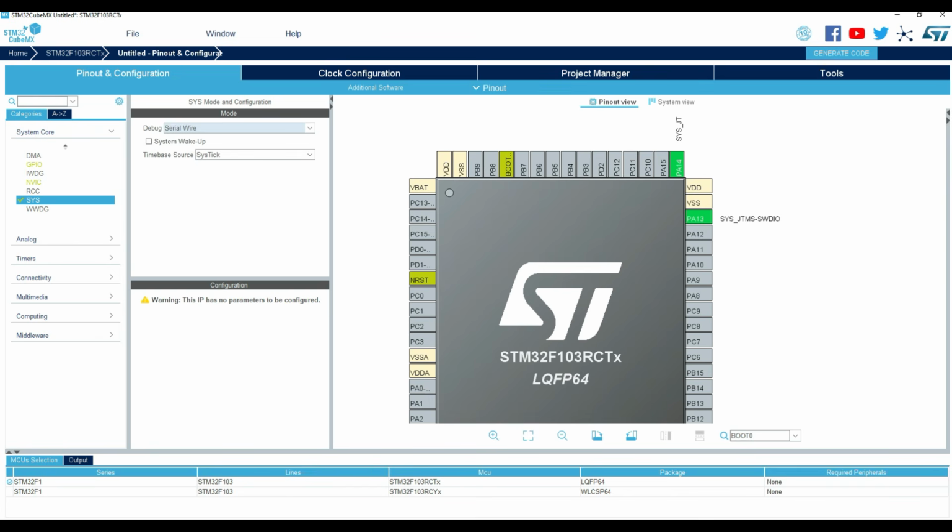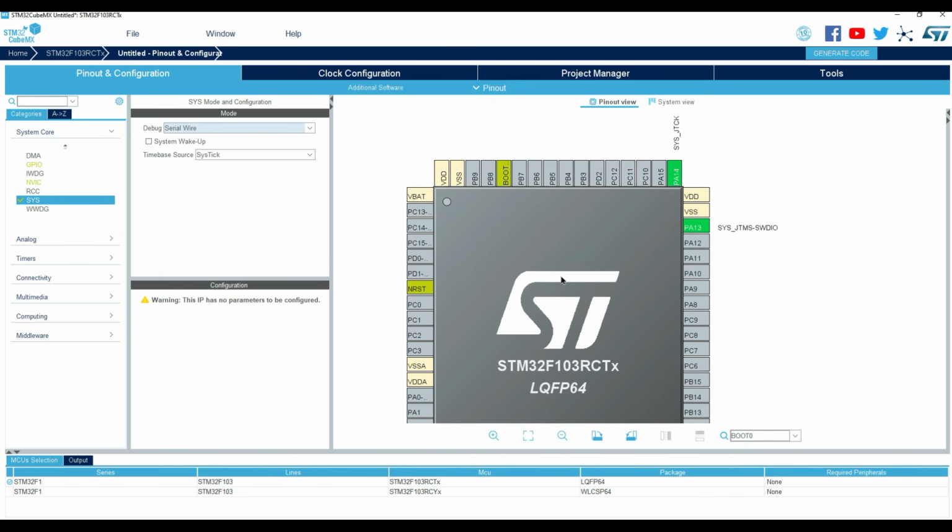By factory default, you cannot change PA13 and PA14; they have a permanent SWD function. They are not regular GPIO. After reset, SWD mode is automatically enabled, as on an original Nucleo board. So that's why we need this. If by mistake we change it and it is not connected, you might get connected but still see no device found, work sometimes, fail other times, and PA13 shows low constantly.